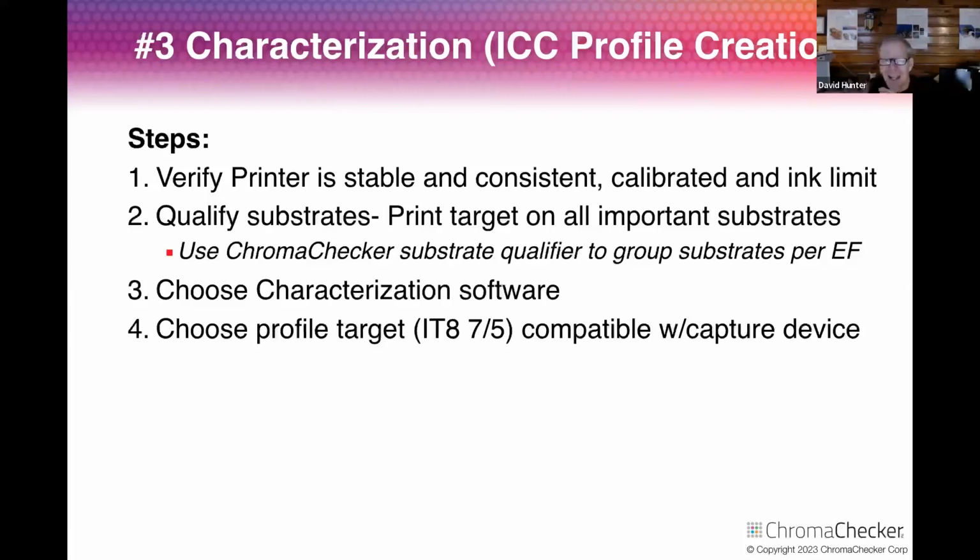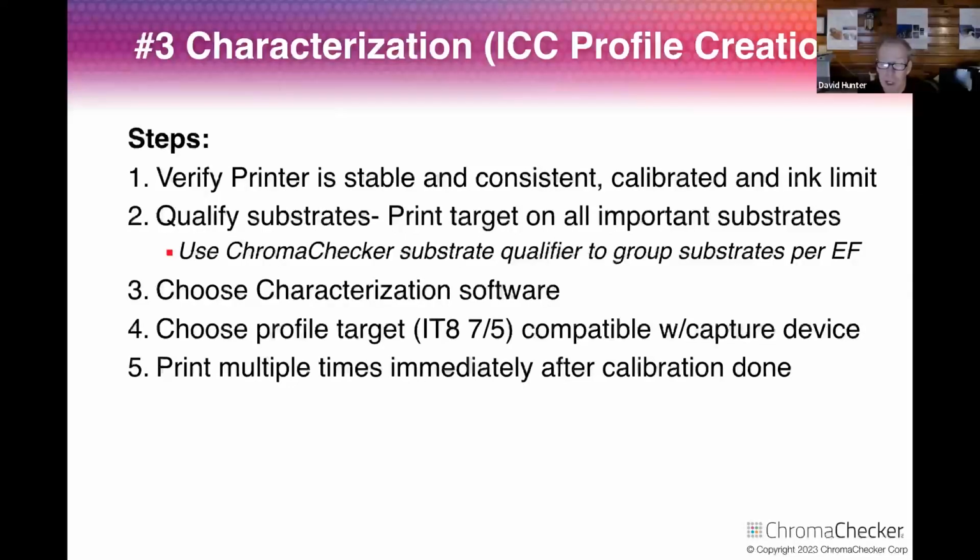So you need to ensure that the instruments are aligned so that when you start mixing and matching prints and characterizing your printers and verifying the printers, your instruments are not playing a role in making a huge difference between these situations, because it's telling you there's a huge difference, but visually it's identical. There is no difference. So it's what we'll call a false fail, in that the instrument tells you there was a problem, but there's really not. It's the fact that your instruments are not aligning to one another.